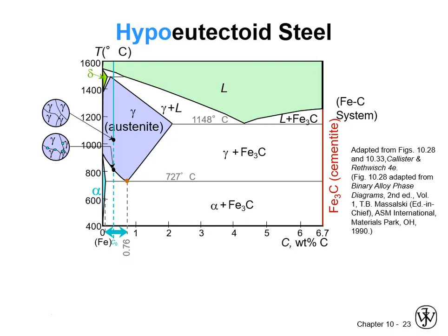So when you think about grain refining in steels, it starts up at the high temperature phase, even if that phase isn't there when you use the material, it's set the scale. So we grow that alpha, and it connects eventually. It becomes continuous, starts growing along the prior austenite grain boundaries, and then whatever austenite is left forms eutectoid.